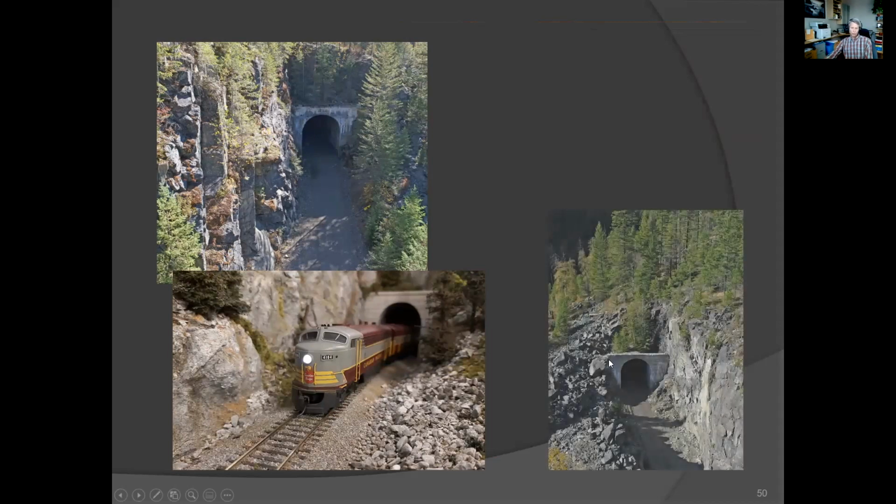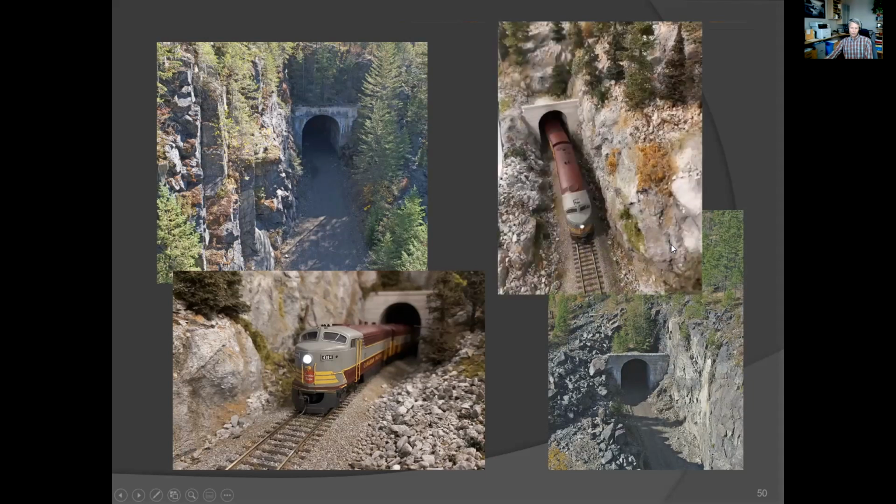This is an interesting one because this tunnel portal is about 25 feet back or ahead, I guess, of where the original tunnel rock bore was, which is back here in the trees. So the concrete liner you can barely see here. The concrete liner is actually exposed. These trees and all this are actually sitting on top of the concrete liner for the tunnel. So my theory is that they built it further out just to provide some protection to the track in this area here from rock falls and whatnot. So we built it that way.